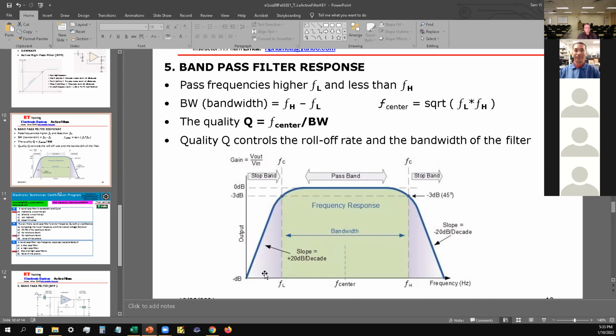Is that correct? Well, you keep on increasing your frequency, and at the center you're going to have the maximum voltage. Say this is like 10 volts, for example. At the maximum here, you're going to be getting 10 volts. Here it would be less than that, like 9.99 or 9.98 or anything like that. So at the maximum, okay, so it does come to a point. Yeah, it would come to the maximum, and then if you keep on increasing, it would keep on decreasing, going back down this way. And therefore, at the maximum point, that would be your center frequency.